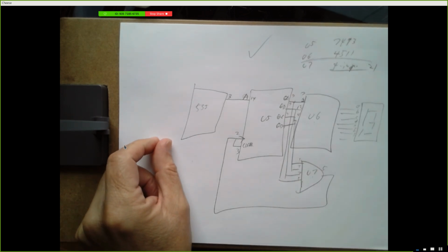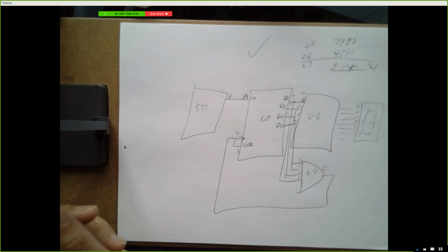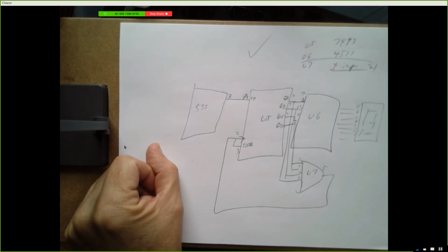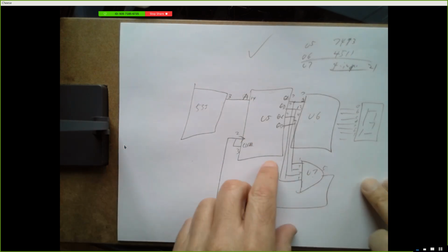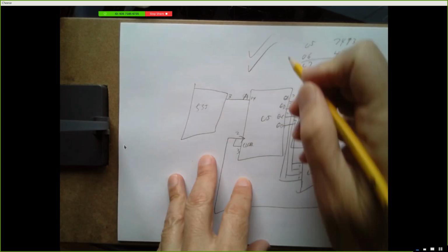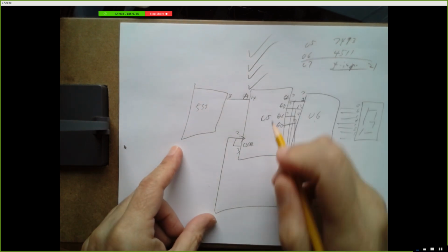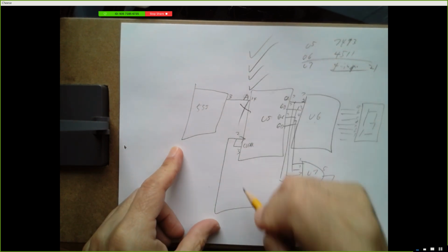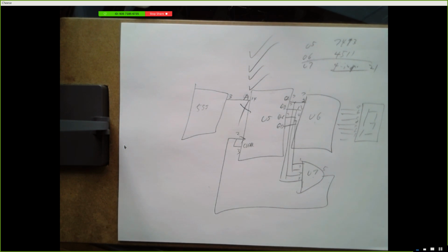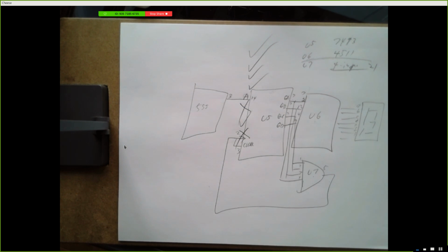Then step 2 of the test plan says, now flip this switch to the off position, and these two LEDs should turn on, and the third one should stay off. They flip the switches, look at the LEDs, and say, yep, that still works. If your circuit is correct, you'll end up with a whole bunch of check marks. If it's not, somewhere there'll be an X. Test 5 didn't pass, and maybe test 7 didn't pass.